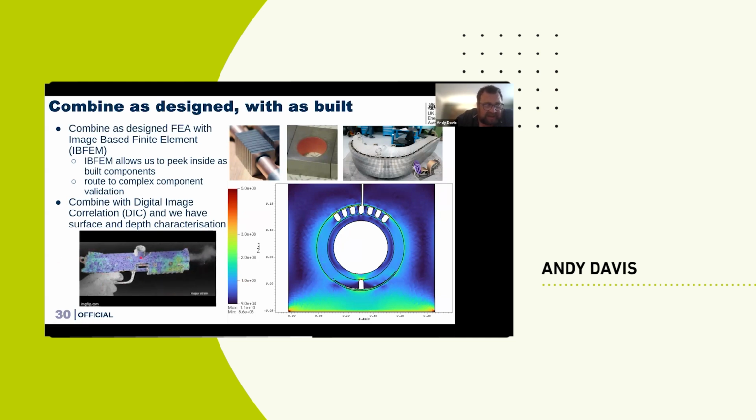So this, I guess, is a paintball gun. Got a paintball gun, yet firing a marble. This is covered in speckle paint, so it's kind of like you spray paint it first of all white and then cover it in these black speckles. And what you can do if you take lots and lots of photographs, you can between each image see how those speckles are moving around, and this gives us a live view of the mechanical strain or the displacement of how this component, in this case this paintball gun, is actually mechanically changing.